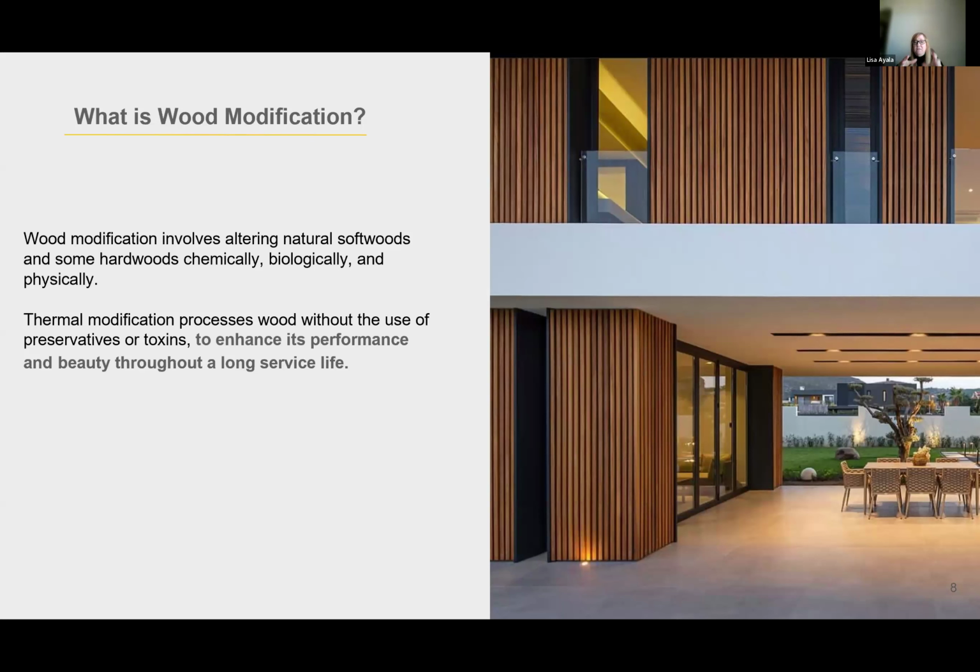Wood modification is very different from wood treatment insofar as wood modification does literally change the wood at the very core level, or the cell level, or the molecular level, whereas a wood treatment basically takes wood and will surface treat it around the edges, and then the inside of the wood is not protected or changed. Modification is a permanent change.